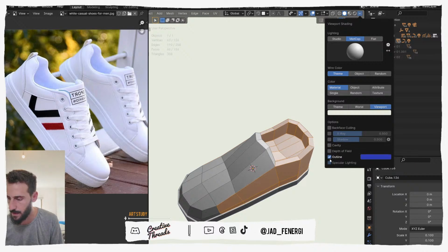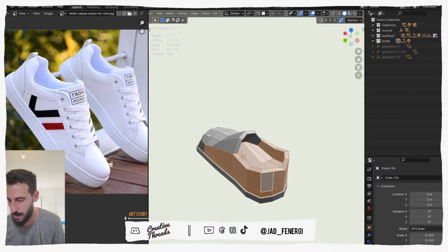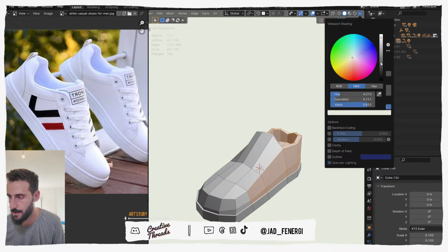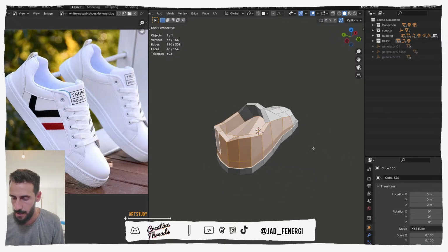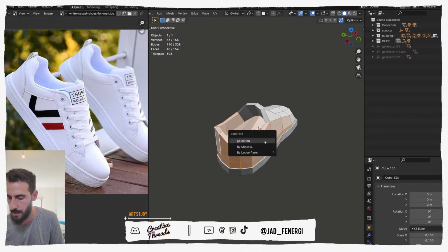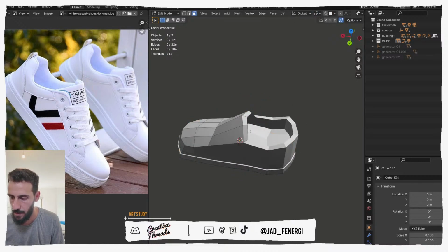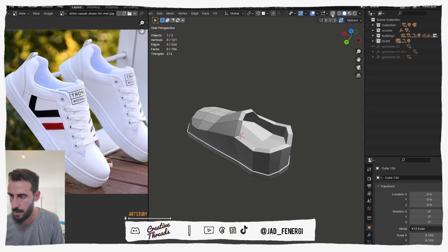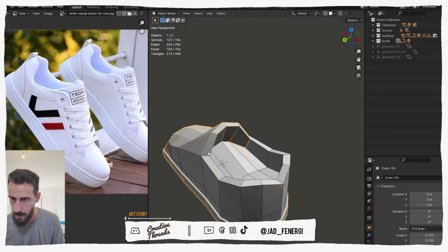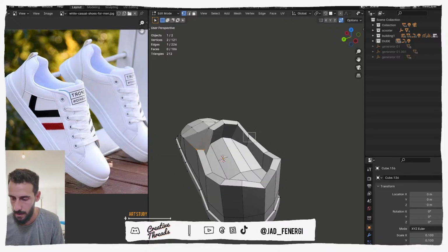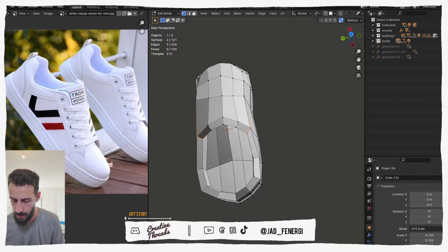We need cavity. I'm gonna turn off cavity a bit because it's darkening the screen. Let's go for something a bit gray so we can see better. So this is the selection that we want to work with. Press P, selection, right? Also the wireframe could be a bit darker. So press Tab, select these two objects, scale on the Y by a little bit.